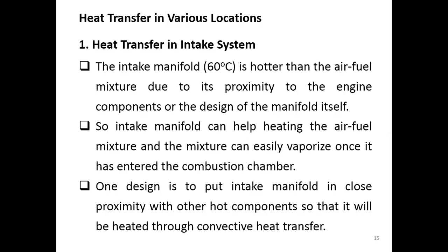To do this, one design is to put the intake manifold in close proximity with other hot components so that it will be heated. The intake manifold itself can be heated through convective heat transfer. Just put it close to the hot components and let the convection mode do the heat transfer to the intake manifold, and then the intake manifold does the heat transfer to the air fuel mixture.